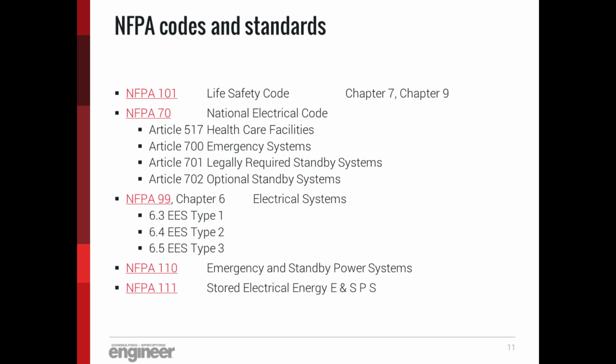NFPA 70 has Article 517 that refers to healthcare facilities, Article 700, emergency systems, Article 701, legally required standby systems, and Article 702, optional standby systems.